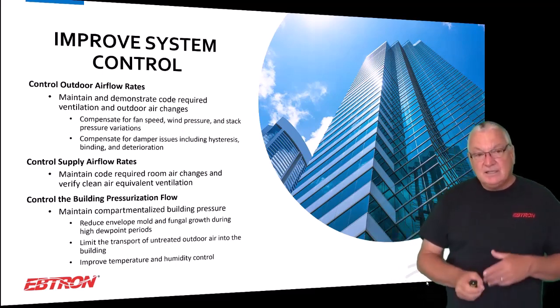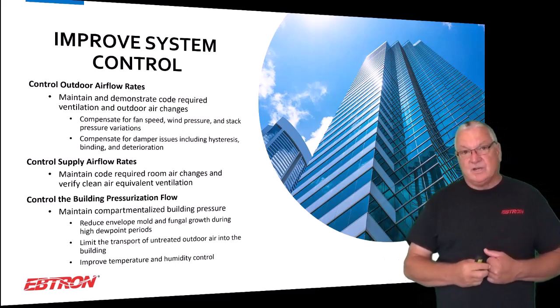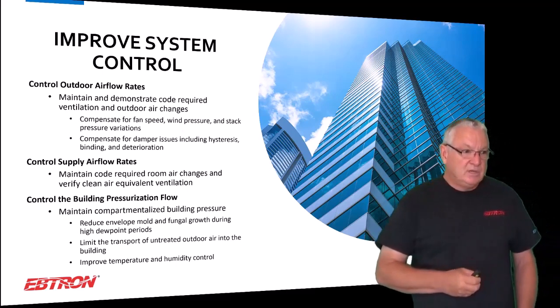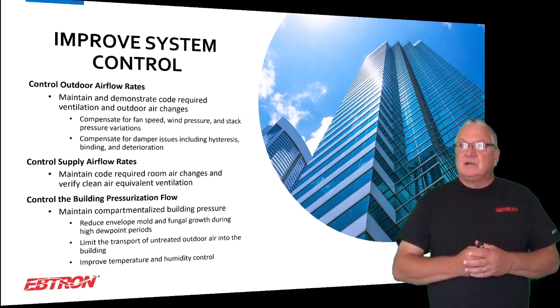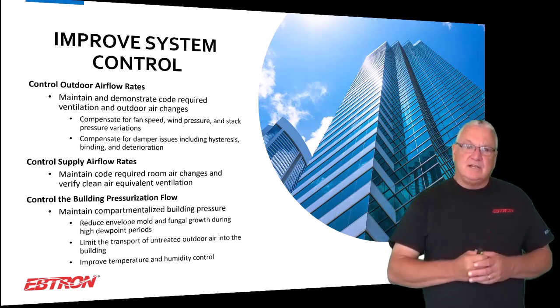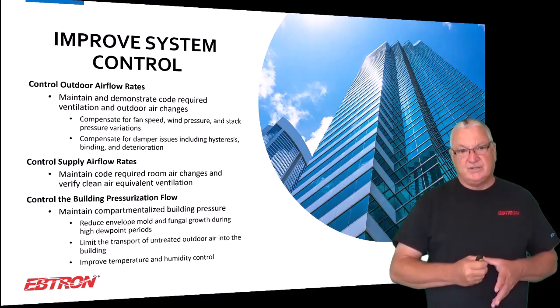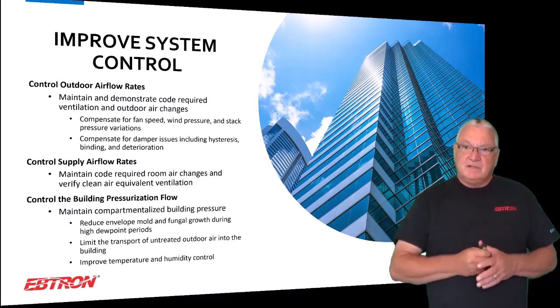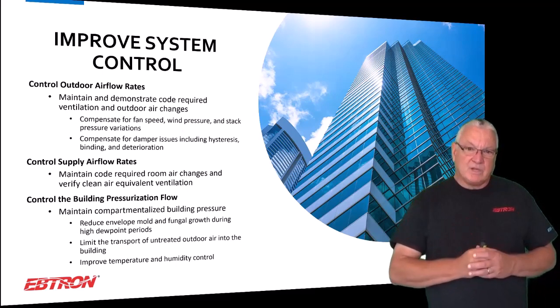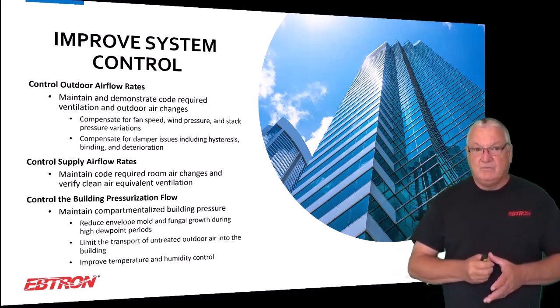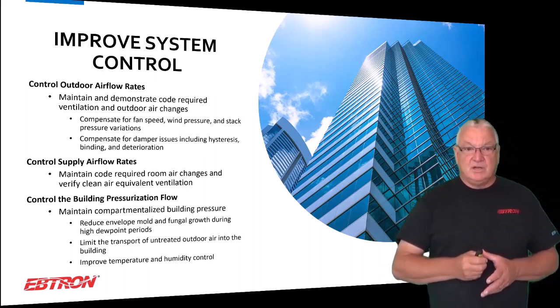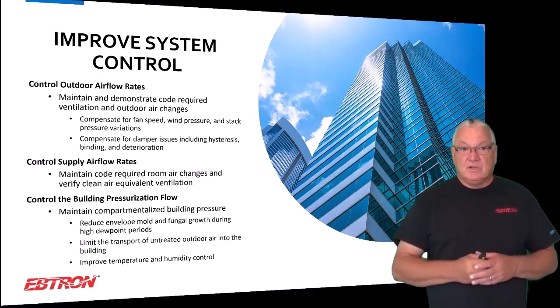Okay. The other thing that we need to do, and we need to think about it more today than we used to. We always think about healthcare facilities and supply airflow rates because we're concerned about room air changes. Okay, but some of the new energy changes that we've seen, and requirements like Standard 241 for infection risk management mode, really talk about equivalent ventilation.